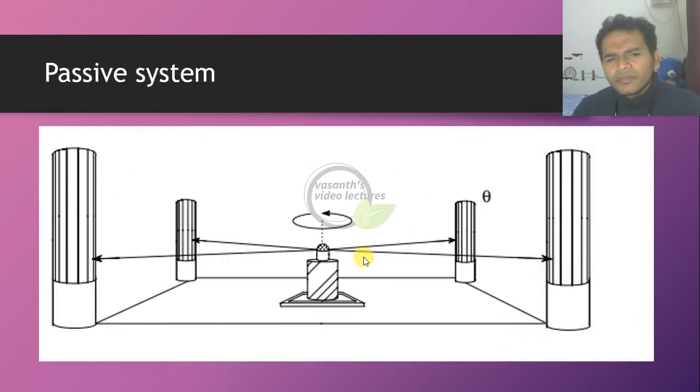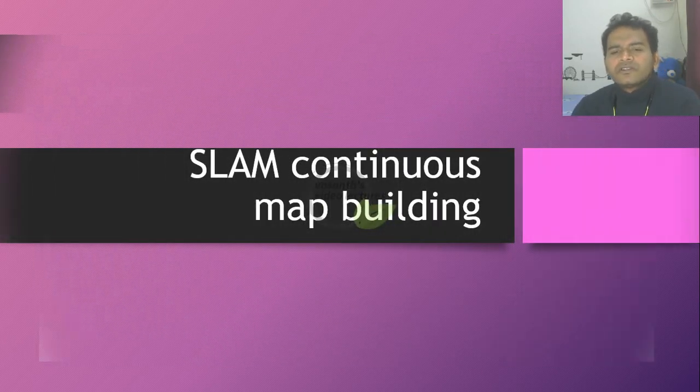localization. Coming to the passive part of the same, you have some small towers which are generally passive, and they are retroreflective. These retroreflective sensors will be fed by one sensory input, let us say a laser beam which rotates through 360 degrees. For example, if the robot is moving towards a tower, there would be a distance reduction based on the reflection. That's all about a passive reflecting system, which is fundamentally used in non-contact applications or non-contact mobile platforms.